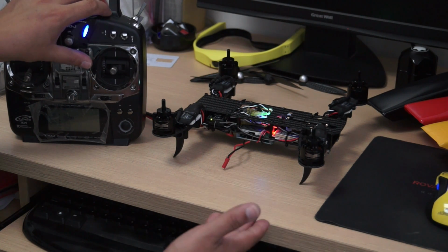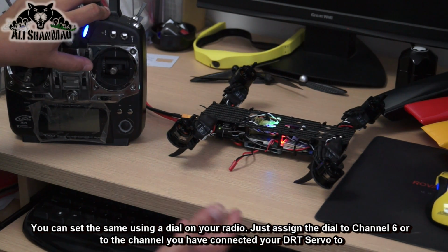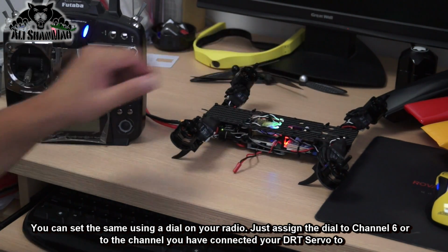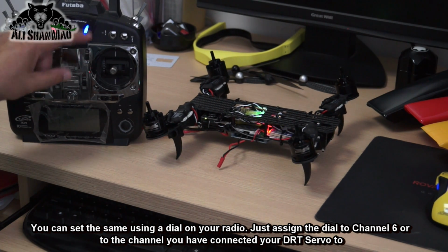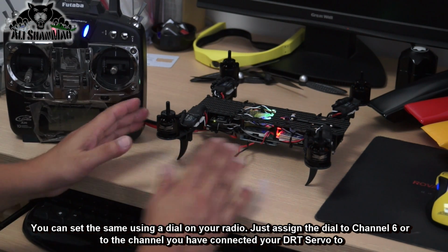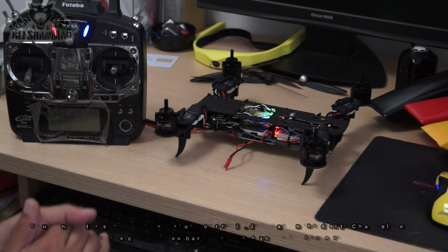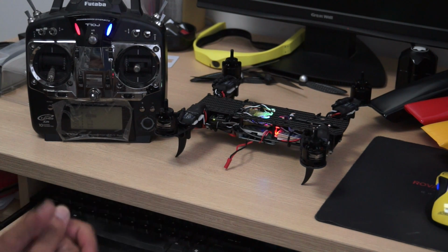So that means this is a completely traditional quadcopter with the rotors tilted, but this is a fixed tilting, and when I want to land, my quadcopter will be hovering this way with the camera looking up. I can always center the rotors using the trimmer. So this way, in the center, the arms and motor mounts are perfectly horizontally leveled, and then using the trimmer I can trim the angle as I want. So that was channel 6 on DT5. Rest, I'm not using any more channels.